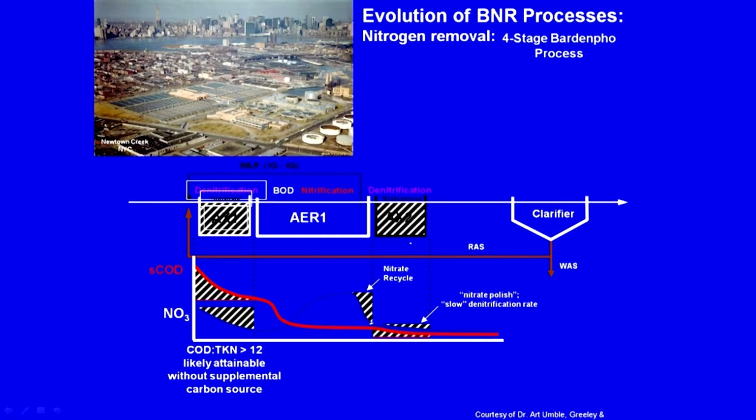So, in this endogenous tank, am I supplying anything? No, I am not going to supply any oxygen, right. I am not going to supply anything. I am not going to supply any methanol. Why? Because I want the residual carbon or organic compound also to decrease. So, I am not going to add any methanol. So, the remaining, what is it now? Nitrate and remaining organic carbon, or endogenous respiration by cell mass being used for respiration will take place. That can affect the quality, but you have to maintain it at the endogenous growth phase.